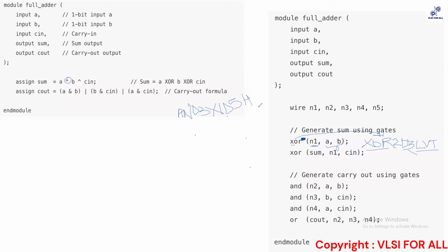This is something which is present in your library. Whatever cell name is present in your library is called your ref name, because that is the way in which you will refer to this cell from your library. It is a very standard format. All the cells, the way they are defined in the library, you have to refer to them, and that is called your reference name.